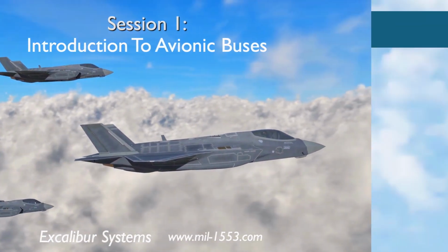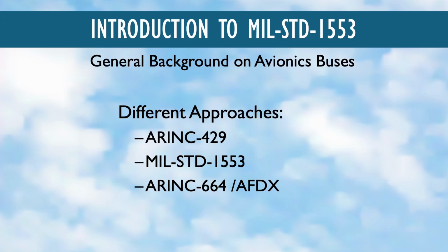applications. An avionics bus is a means for moving information from one part of an airplane to another. For example, getting information from a GPS to the pilot's display screen or from a button next to the pilot to the landing wheel assembly. When we say real time, we mean within a defined time constraint. This constraint may be different for each type of information. The acceptable time between pushing the landing gear button and having the landing gear come down may be longer than the time between hitting the ejector seat button and ejecting.